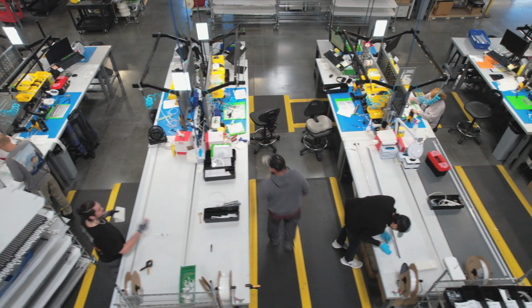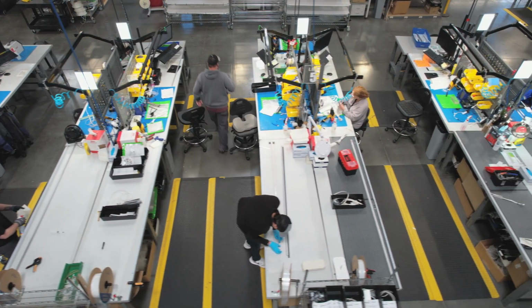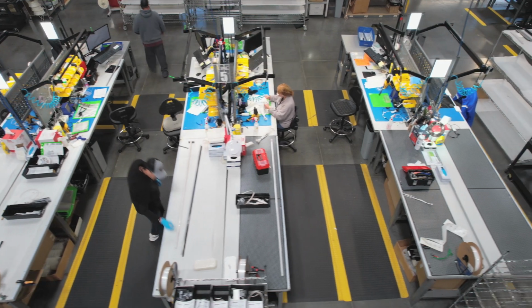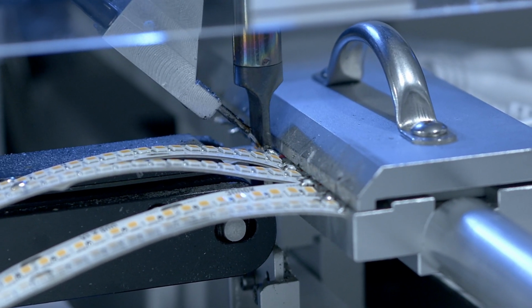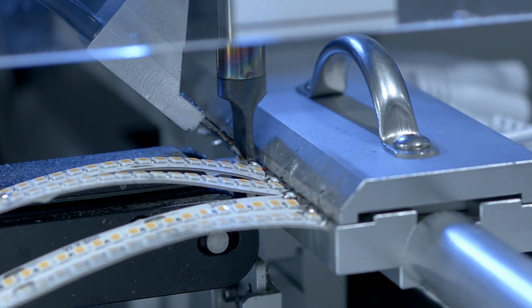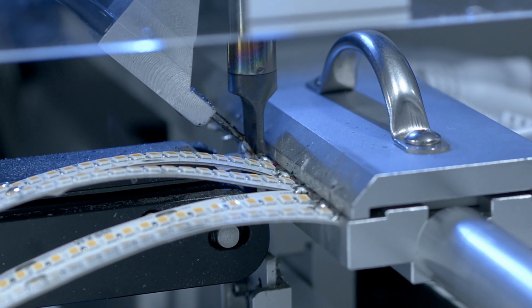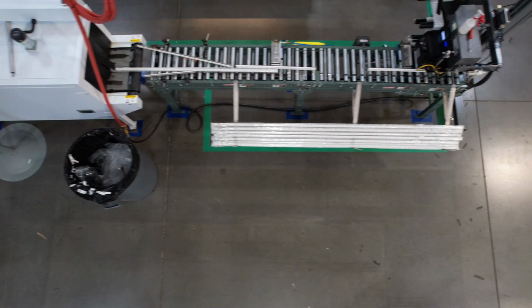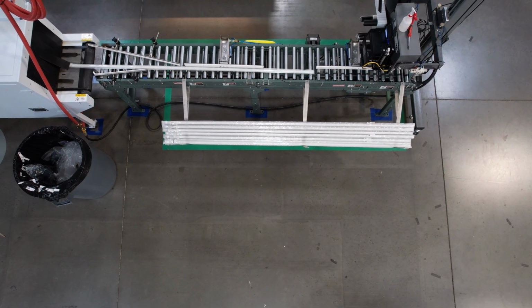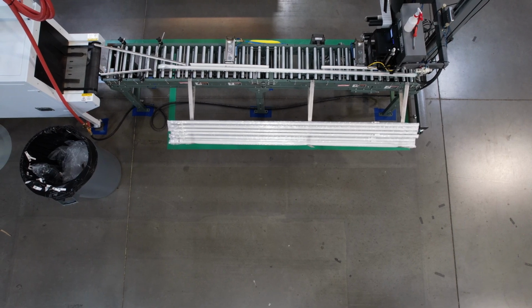We'll take the lengths that you want. We'll buffer about 10 to 20% on top of it, just in case, so you can trim back the tape light. We will then do a factory soldered lead. A soldered lead in tape light is the strongest, but also most low profile connection you can make. And then we'll ship out the channels in bulk. This way you can cut the channel to size and still do the assembly in the field.